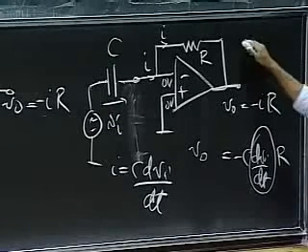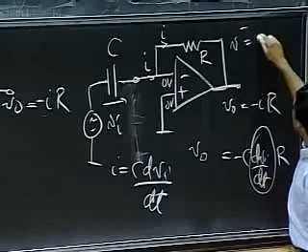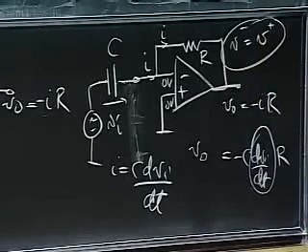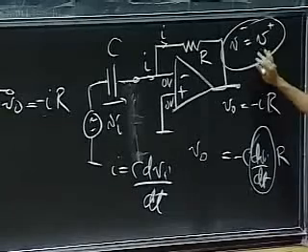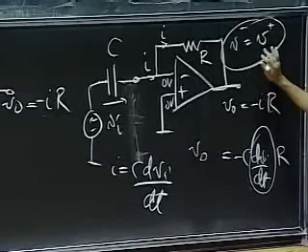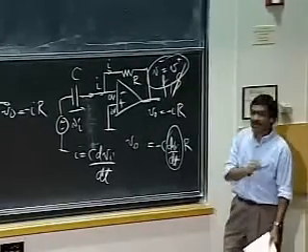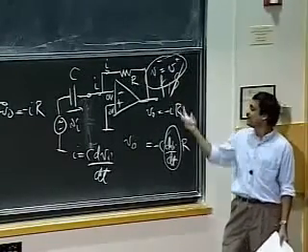Okay, so remember this as a closing thought. Remember this V plus more or less equal to V minus trick, and to the extent possible, simply use that trick to analyze op-amp circuits under feedback and not in saturation. Just remember these two.